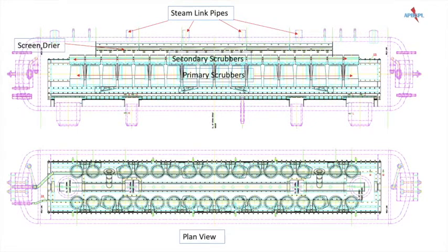The steam drum also performs the following functions: Mix the feed water with the saturated water remaining after steam separation. The feed water lines are submerged in the drum water and must be arranged so as to avoid discharge of cold feed water against the bare drum shell, as temperature variations can cause severe thermal stress in the thick drum shells. Mix the corrosion control and water treatment chemicals.